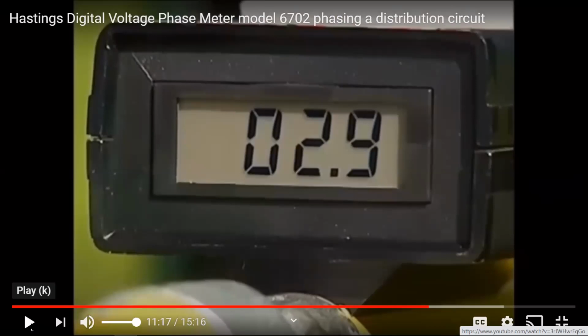So there's no real direct contact between the center conductor of the primary and ground. You need to charge that cable up for a little bit until it eventually flashes over to ground, because there's a puncture in the conductor. So it's making its way through the insulation to the outside ground. That's what they call a puncture cable.